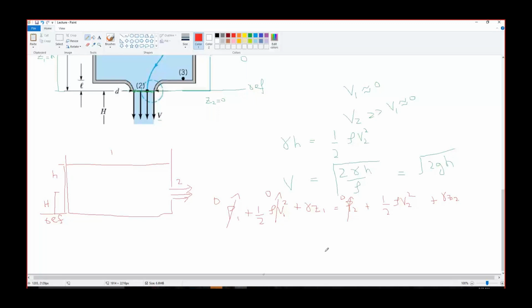Yes, sir. Sir, instead of the height, capital H minus H1 will come. Basically, again, we will be considering only this height, which is the free fall height from where the fluid has to fall. So let's say this H dash, right? So there will be no difference in the equation because it will only be considering the difference of the two heights, two elevations. Clear?